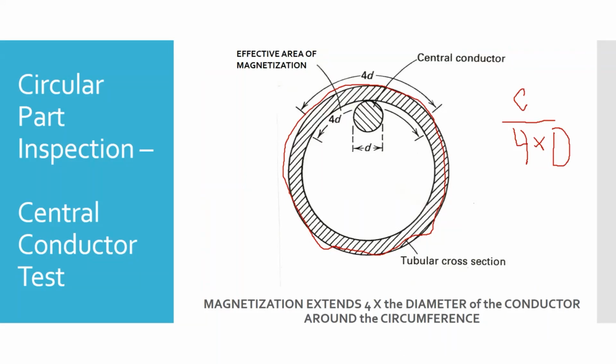The way you would do it is you would have your ring or your gear hanging on the rod. You would run current through it, put your fluid on, stop putting your fluid on, stop the current. You would do an inspection of it. Then you would turn it, run current through it again, put fluid on, stop, inspect it again, turn it again, and do that as many times as you need to do the full outside.